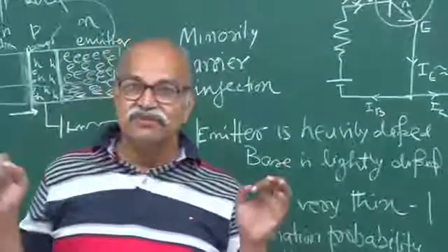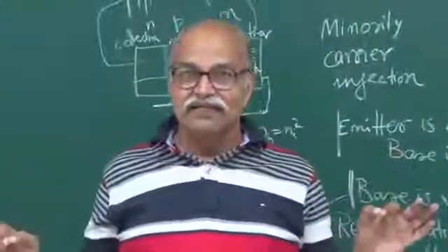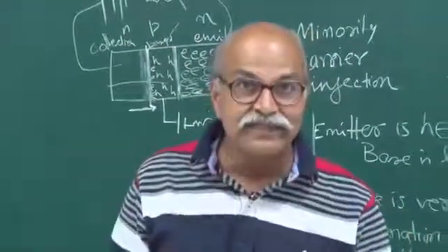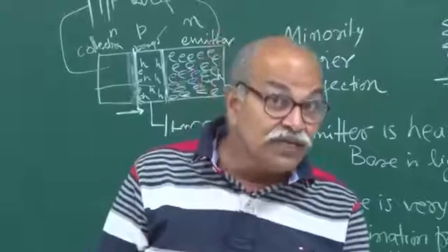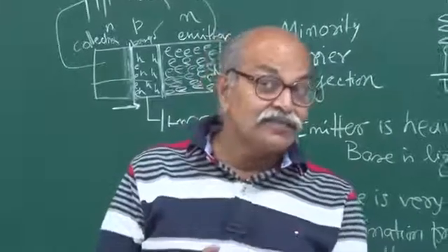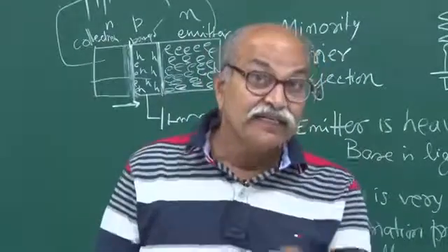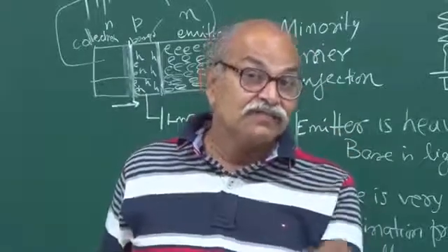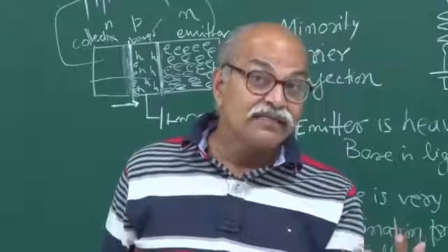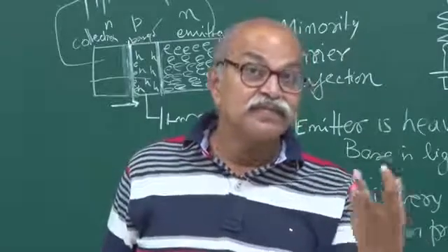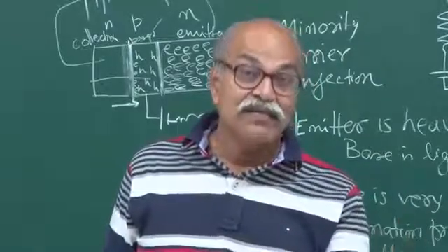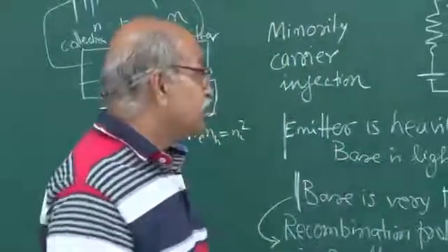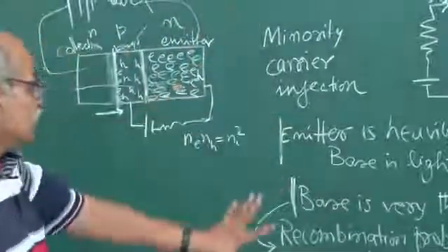So you have to very clearly understand that the current in the transistor circuit is crucially, and that is why the transistor is made in that fashion, it crucially depends on the thickness of this layer, the sandwiched base layer, and the level of doping, the concentration of doping in emitter and in this base, and then of course the reverse biasing and forward biasing and all that. So this is how the current goes.